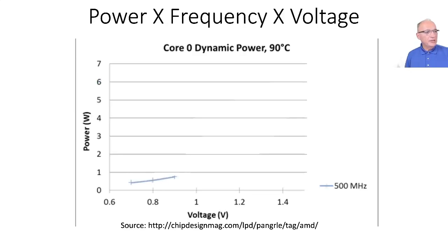What we have now is a different curve. This curve is trying to show the effect of the frequency on the power voltage curve. So if I have processors running about 500 megahertz, I can operate them at a lower voltage, and therefore I consume lower power. As I increase the frequency, I can no longer operate at the lower voltage. So there is a dependence also between the voltage and the frequency in which I can operate the processor. And as I operate it, the power consumption increases.